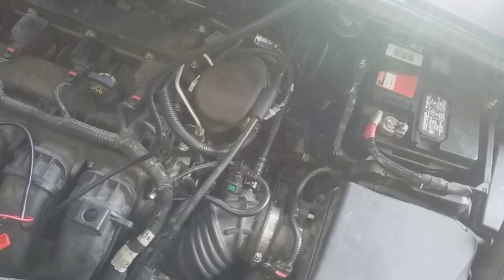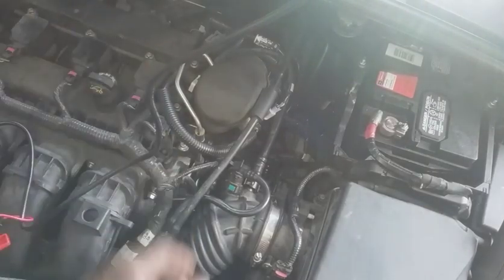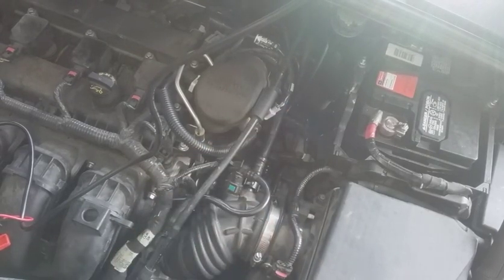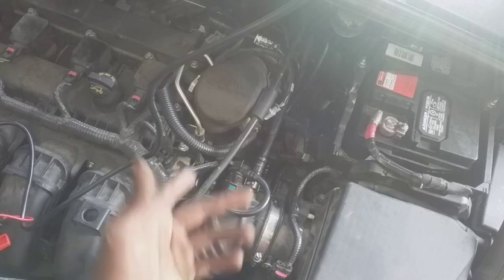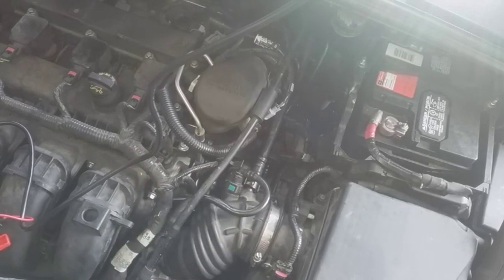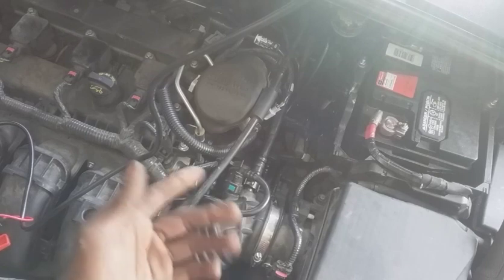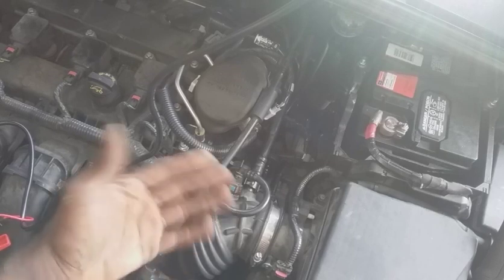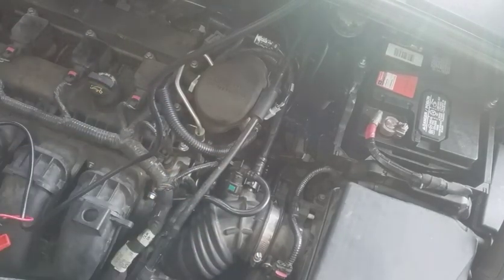So don't change the wideband or oxygen sensor upstream. Don't change the mass airflow sensor. Follow the trail based off of what the customer states. If there's anything else, I'll update. But other than that, this car was pretty obvious that we found the issue. There was no wideband issue, no mass airflow issue, no overall rich codes as a result of any other thing but that purge valve, despite having a code the first time and not having one the second time.